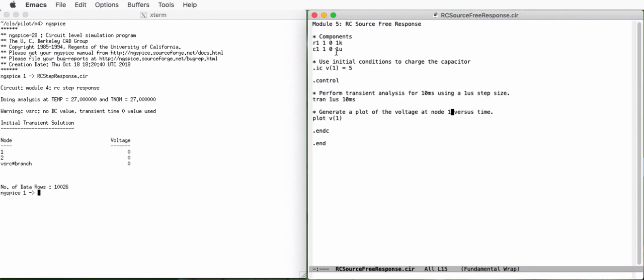The first way was using the exact same netlist that we had for the step response, because you'll remember our pulse waveform went high for 1 second and then went back down to 0 after that. If we zoomed in on that point right after we switched our voltage source back to 0 again, we would see the exponential decay of the voltage across the capacitor. So that would have been one way to do it.